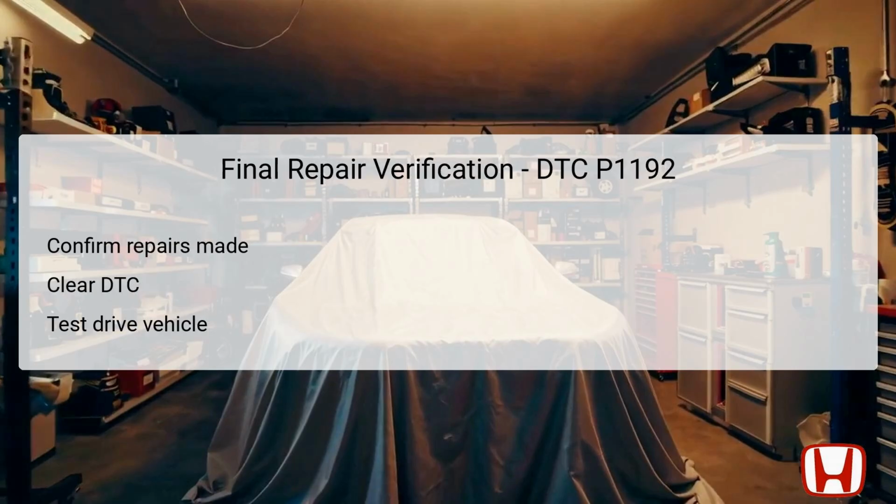After completing all necessary repairs for DTC P1192, it is critical to ensure that proper repair verification takes place. Start by confirming that all repairs made, whether it involved replacing the FTP sensor or addressing wiring issues, are effective and securely implemented. Once confirmed, proceed to clear any diagnostic trouble codes stored in the ECM, allowing for a fresh assessment of the vehicle's performance.